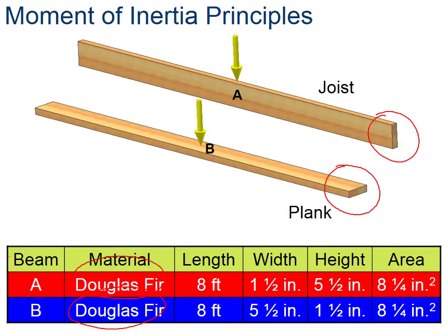If you look at the actual size here, I call this a 2x6. The real size of these boards when they come out is not 2x6. They're actually only 1.5 inches by 5.5 inches. That's all depending on how the board has been cut down into that specific size. So when you actually go to buy these boards, they're not really a 2 inch by 6 inch true size. If you were to measure it, it would be 1.5 inches by 5.5.